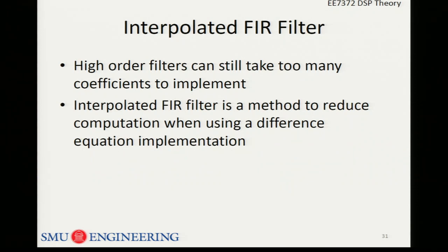So what you're going to have to do is do a difference equation. So suppose, what tricks can you play to still use a difference equation and still get some gains in computational efficiency? And so that brings us to the interpolated FIR filter. So we're going to implement, and I guess here's the rub, we're going to implement an FIR filter with a difference equation and do it more efficiently.